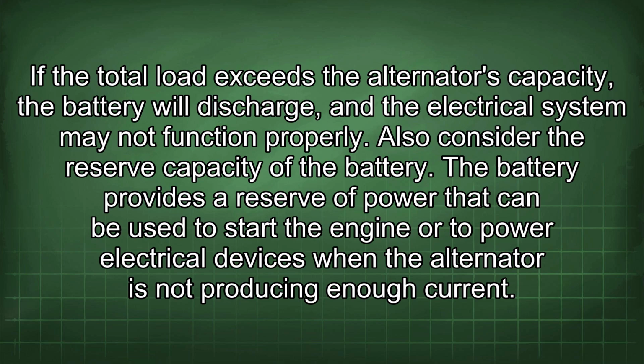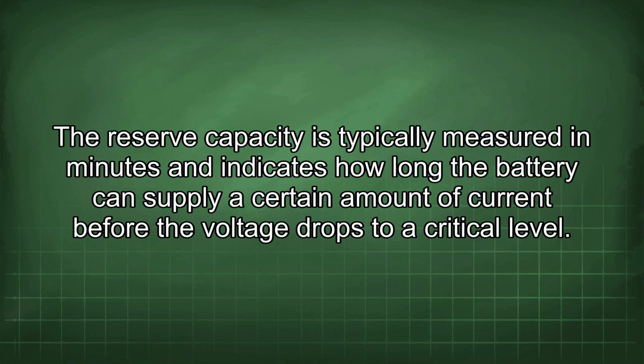Also consider the reserve capacity of the battery. The battery provides a reserve of power that can be used to start the engine or to power electrical devices when the alternator is not producing enough current. The reserve capacity is typically measured in minutes and indicates how long the battery can supply a certain amount of current before the voltage drops to a critical level.